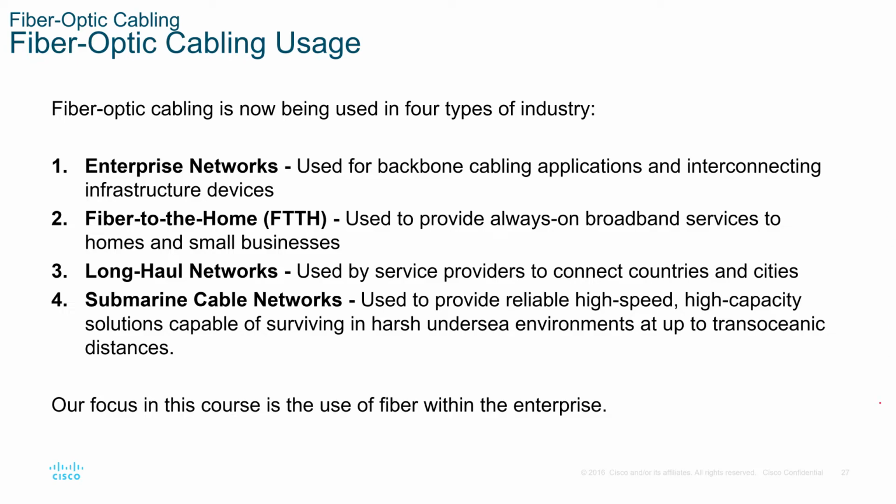Putting ends on fiber used to be a very expensive process in that you had to melt the glass and put it together. The instrument to do that was extremely expensive. Now, there's a simple tool that will just cut the cable, and then there is an end that has a gel that has the same optical properties of the cable that can be crimped on.